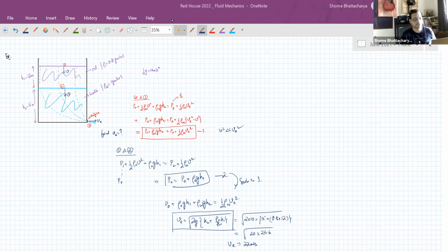Yes, Aditya, you have also mentioned the same thing. So that's correct. So you can think of it like a water tank with the equivalent height H. And that equivalent height H would be what we have inside that bracket over there, H2 plus relative density of oil into H1. So that's also, especially at an exam level, if you remember this concept, you can directly apply this. So it's something easy to work out.